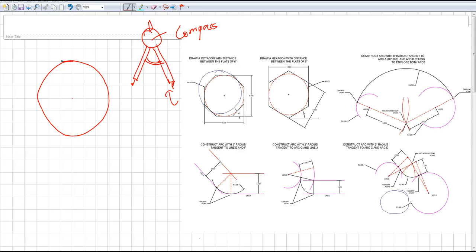So the next thing I would be doing is draw a straight line going down here, draw a straight line on the top, aligning my slider, draw a straight line touching the circle on this side as well as this side. Now what I have is a circle enclosed in a square. Now the next thing I would have to do is draw the 45 degree angle that you see tangent to my circle.